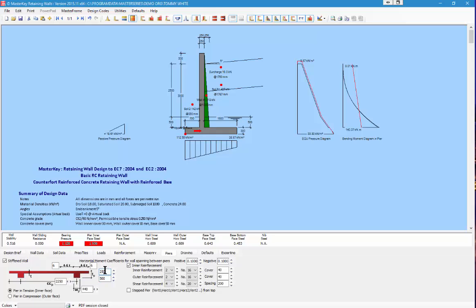That's the top and that's the bottom thickness. It already knows the thickness of the wall. And I'm going to say it's 500. So it's a uniform pier. And since this is going to be concrete, it's going to be 300 wide, and we'll make them at 2 meters apart.